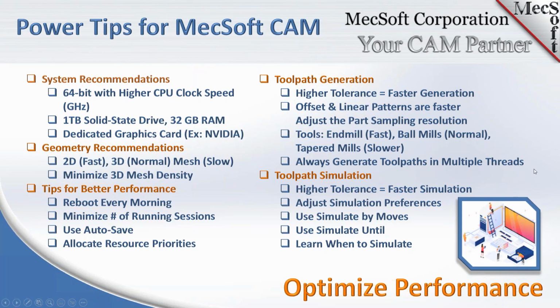Simulation. Oh, Don, I just wanted to break in here again. One of the things you might know that Don's talking about, toolpath generation, applies mostly to 3-axis machining, and higher, 3, 4, and 5-axis machining. It does apply to 2-axis also, but the speeds of computation in 2-axis is so fast that you wouldn't even notice it. So that's the point that I want to emphasize here. If you are doing a lot of 3-axis sculpted surface machining, then these points are important to keep in mind.